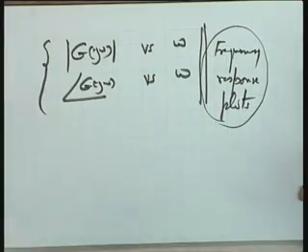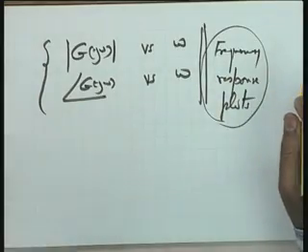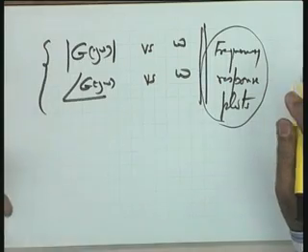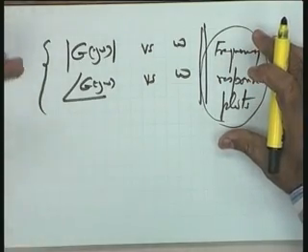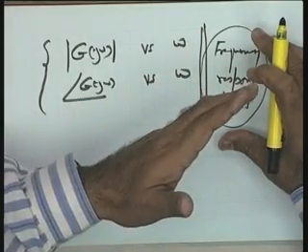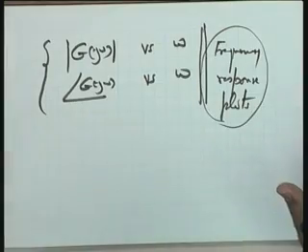So at this point, it should be very clearly understood that though all through our discussion from now onwards our concentration is going to be on frequency response plots, and though they have been obtained experimentally or otherwise from the sinusoidal response of the system at steady state, they actually constitute the complete mathematical behavior of the system, both transient as well as steady state, because the Fourier transform is a link between the transient response of the system and the steady state frequency response of the system.